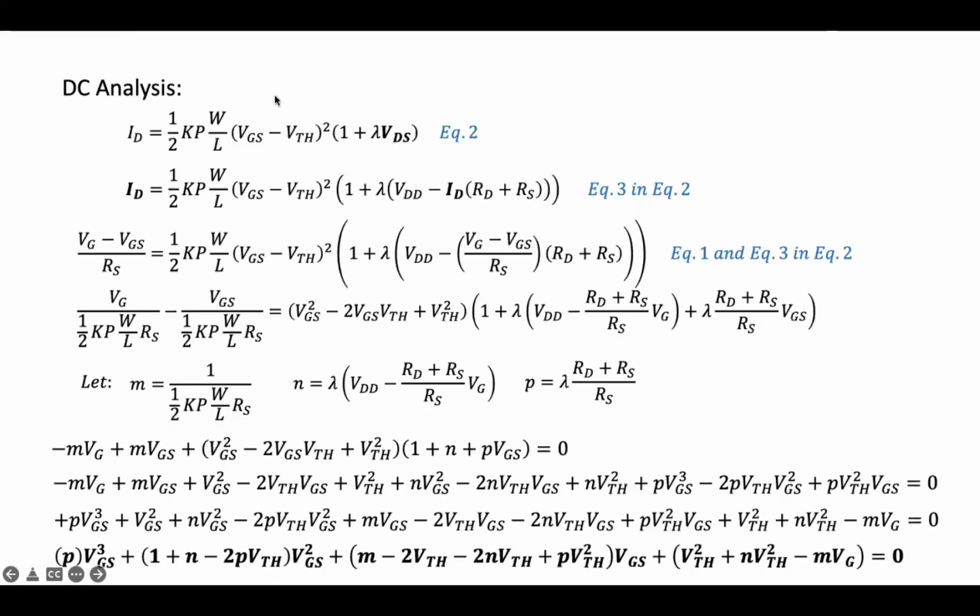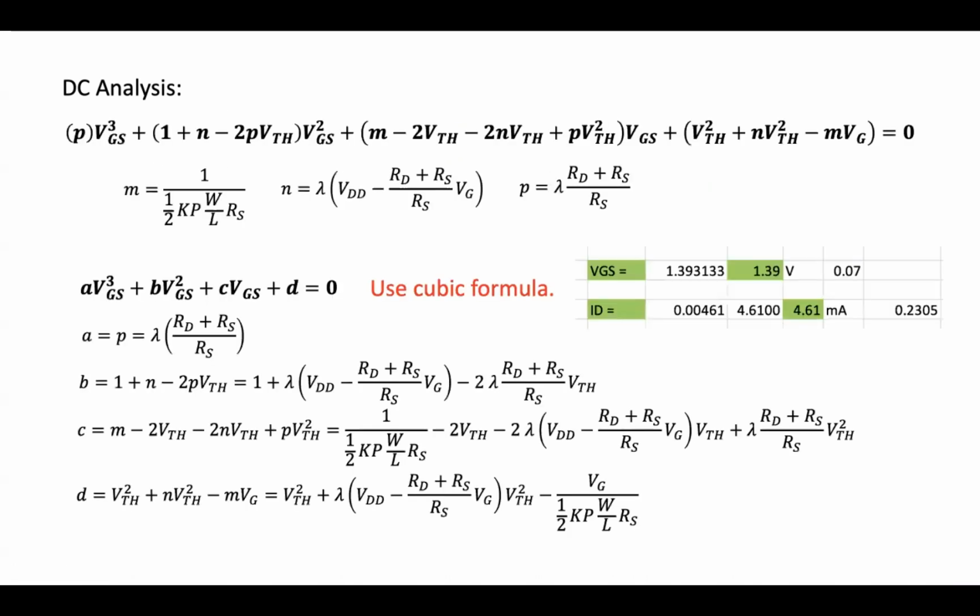Medyo malayo ang balik, no? Alright, dito siguro. So from the transistor model, we have Kp, we're given with the parameters. Meron tayong Kp, lambda, then the W over L, meron ding value to. Hindi ko lang naipakita sa given, but I used a certain value for the width and length in my hand calculation. So that's why we're able to compute for a certain value of VGS equal to 1.39 volts.